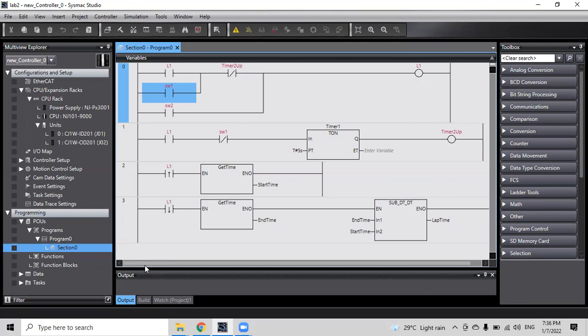All right, so you can read the first page of lab 2, so you know what the application is and why the logic is like this. See exercise 2, the bottom here, the first page. Use TON on-delay timer instruction in a ladder program to make the single-way escalator program smarter in energy saving.